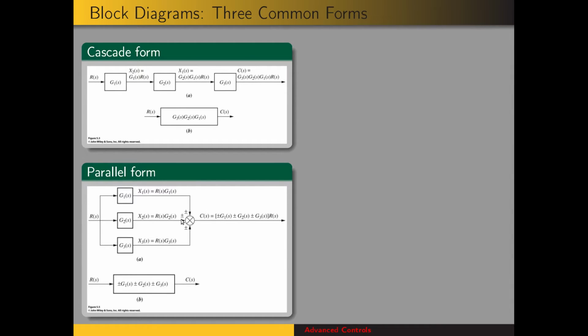And note the plus minus, the signs stay the same. So if they're all added in the summing junction, then they're all added, or if any one of them is subtracted in the summing junction, then it's subtracted here in this sum.